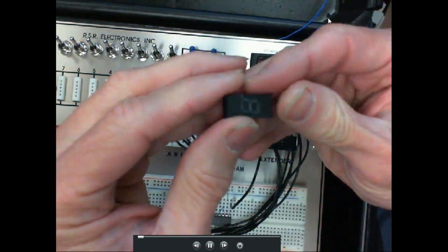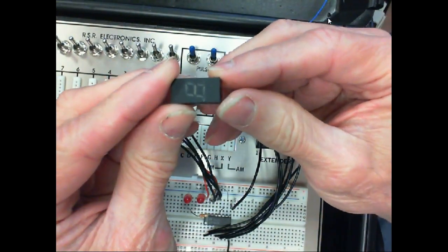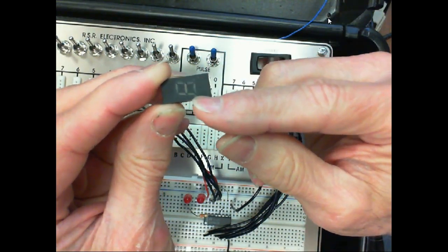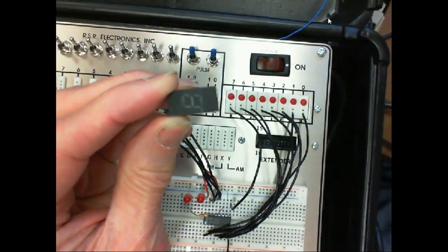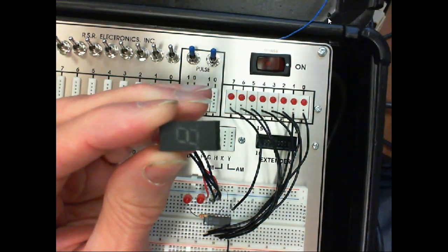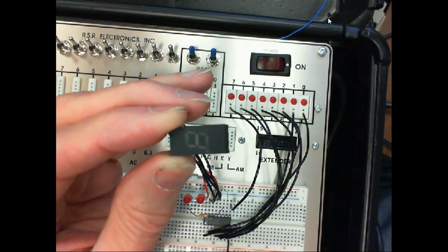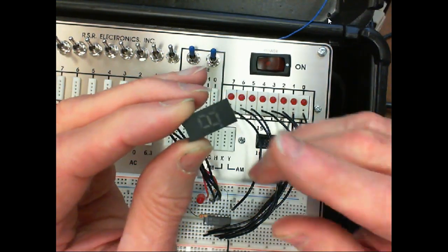So this is the 7-segment display I'm going to wire up. And you can see the actual 7 segments. Then it's got 2 decimal points, but only one of them's wired up. They have a standard lens on this. So one of the things, when you buy these, you have to specify whether you want common anode or common cathode. And then you specify which decimal points you want. You want them on the left or you don't want them on the right. It all depends on this.